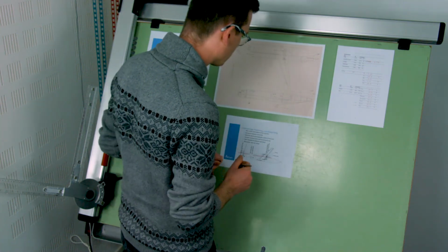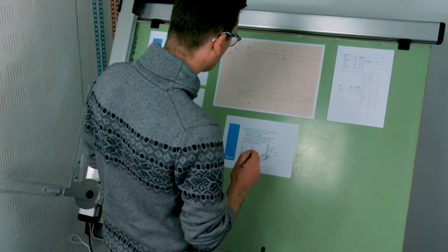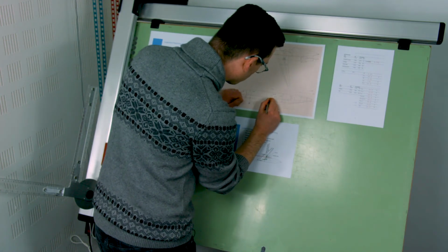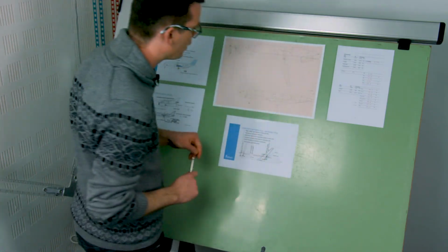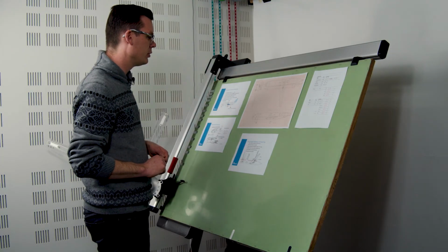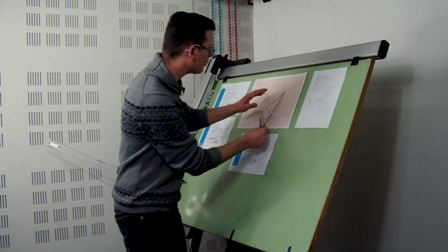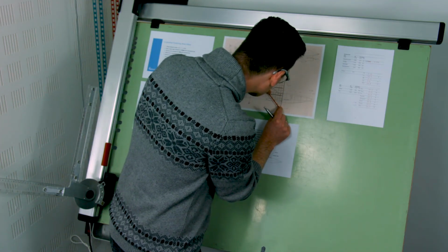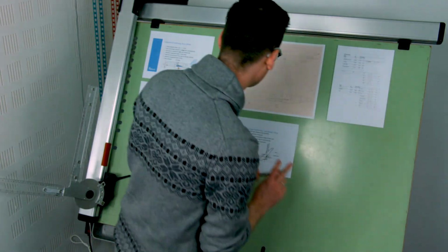That's actually quite desirable. I'm going to put in the kink also in just a little bit, but let me first draw the new root profile in. There it is. And the next thing I need to do is copy the kink position, which is not going to be very difficult, because it's of course the same position as the trailing edge of the airfoil.